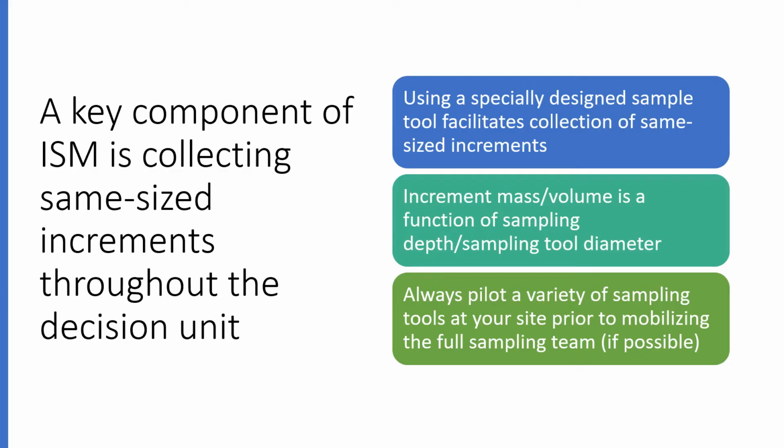A key component of incremental sampling is collecting same-sized increments throughout the decision unit. This is done so that each increment represents proportionally the overall concentration of the incremental sample being collected. Using a specifically designed sample tool facilitates the collection of same-size increments. It helps to make sure that as you move from increment sampling location to location, a same-sized increment is